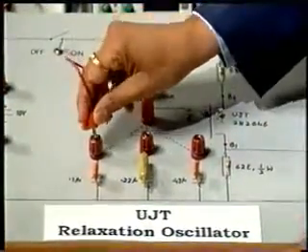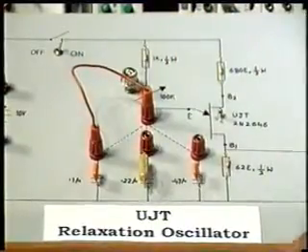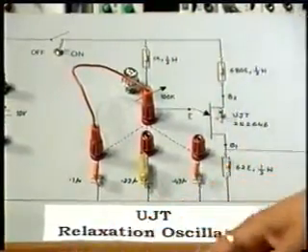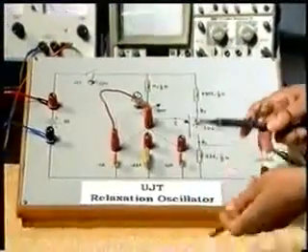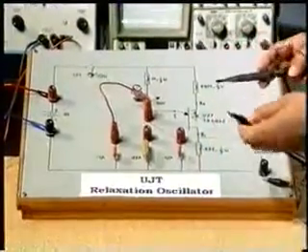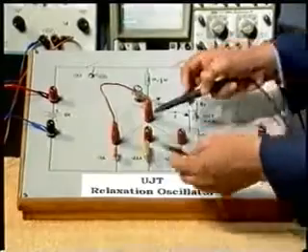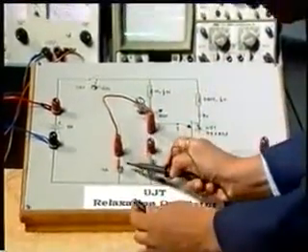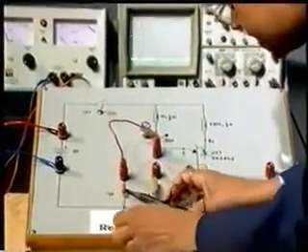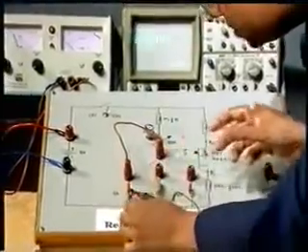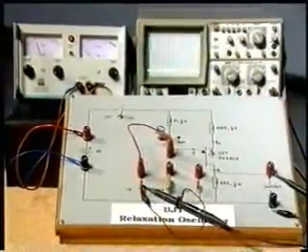So I connect it here. So 0.1 microfarad capacitor is connected in the circuit, and of course potentiometer 100K is now being used as a fixed resistance here. So let me check up the output. Connect the probe across this capacitor, which is 0.1 microfarad, and you see here is the output coming.